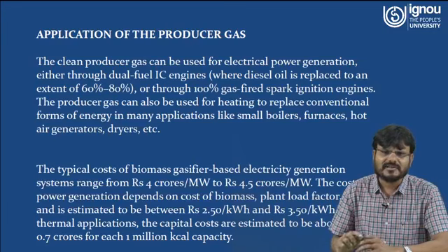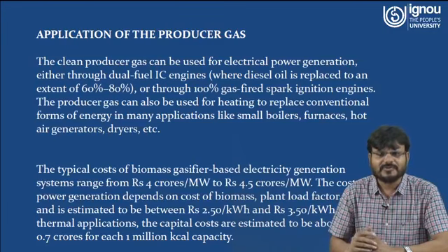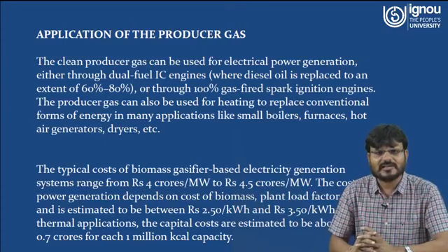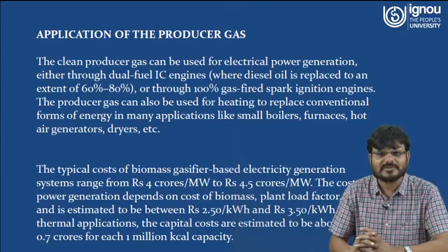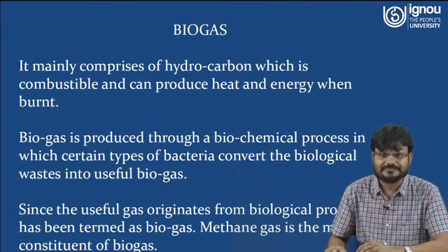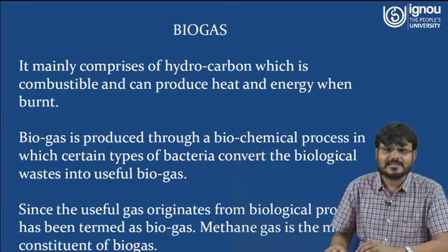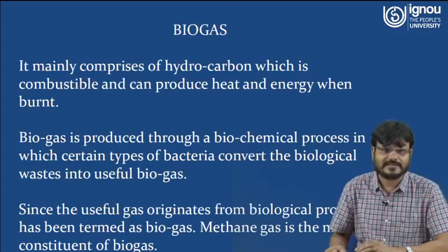That means if you are generating 1 unit of electrical energy, the cost will be around rupees 2.5 to 3.5. For thermal application, the capital costs are estimated to be about rupees 0.5 to 0.7 crore for each 1 million kilocalorie capacity. Now the next and last topic is biogas.